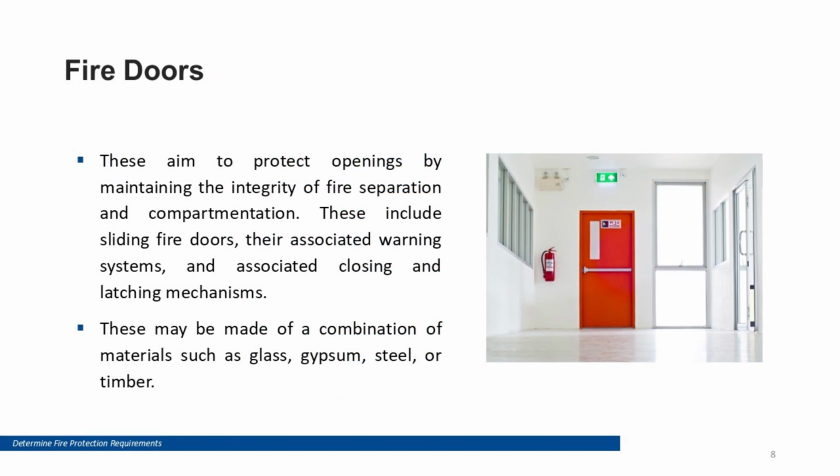Fire doors. Fire doors protect openings and support compartmentation by maintaining the integrity of fire separation. Correct door type, installation, closing mechanisms and maintenance all matter, because a fire-rated wall is not effective if openings are not properly protected.